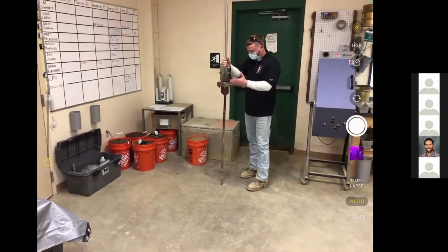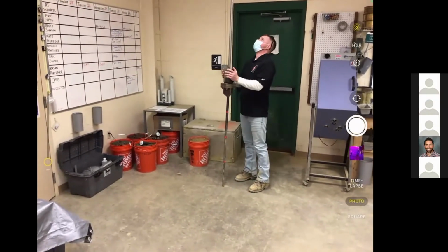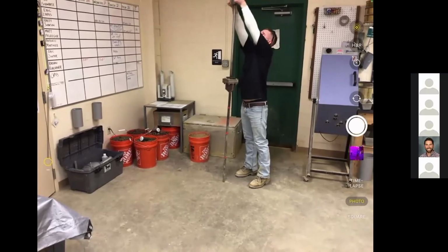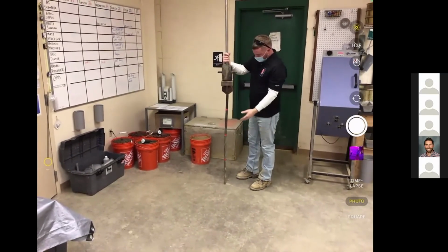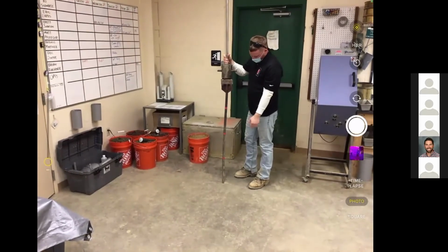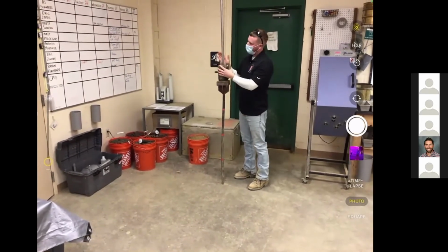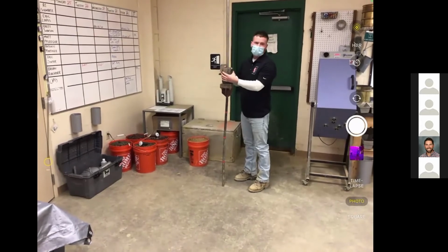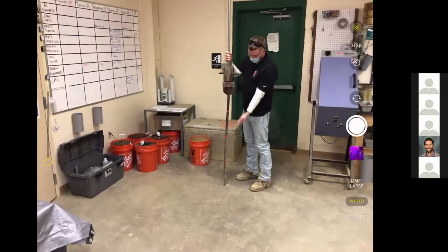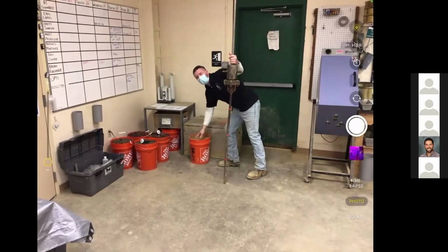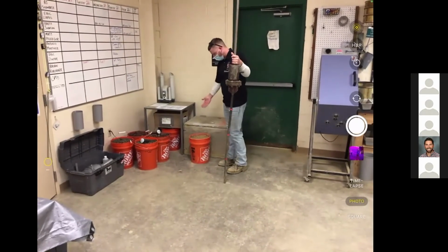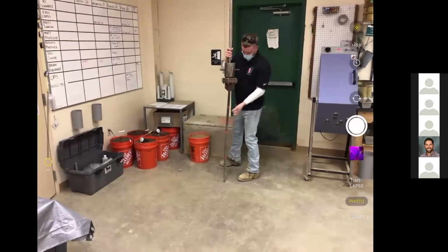We have a 25-pound weight that's lifted 3 foot all the way up and falls freely. Each foot has its own measurement. We are going to document the number of falls from the hammer in each foot. This bucket of soil would be our subgrade bottom. Bottom of excavation, bottom of footing.